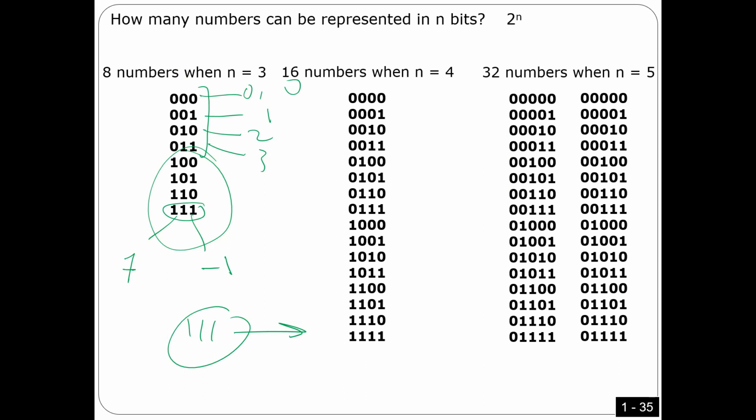So this is completely different from positive or negative numbers, because for positive and negative, I can know if the number is positive or negative from the most significant bit. But how is the hardware going to interpret this number as positive and do the calculations this way to give me a correct answer, or interpret it as negative 1 and do the calculations this way to get me a correct answer? The answer is the hardware doesn't know.